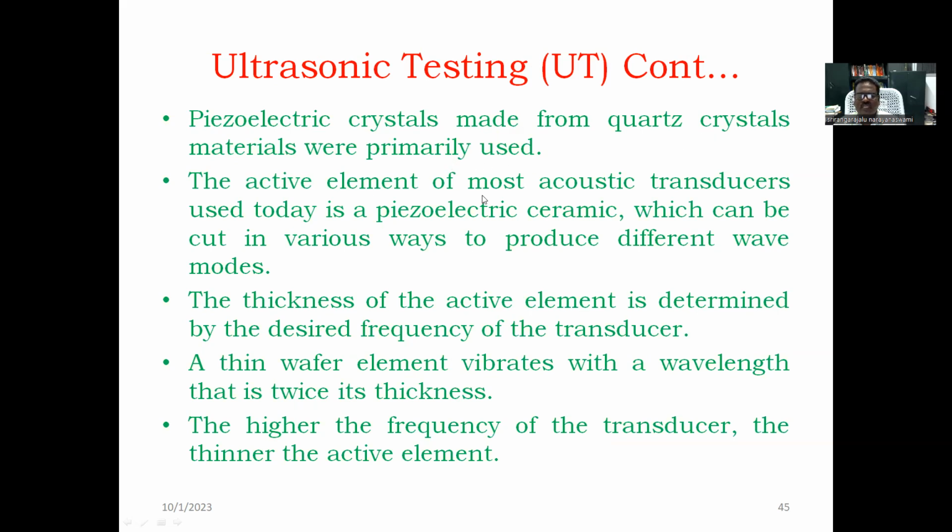The active element of most acoustic transducers used today is piezoelectric ceramic, which can be cut in various ways to produce different wave modes. The thickness of the active element is determined by the desired frequency of the transducer. A thin wafer element vibrates with a wavelength that is twice its thickness. The higher the frequency of the transducer, the thinner the active element.